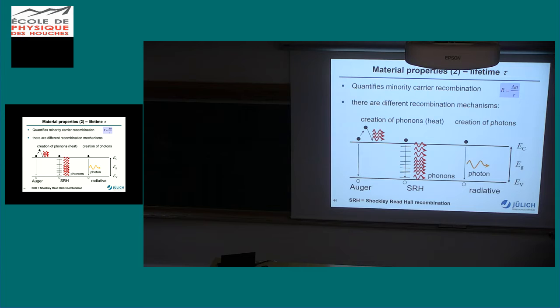But it's also important, for instance, in silicon. Why is it important in silicon? Because in silicon the radiative process is very slow. Silicon is an indirect semiconductor with a low absorption coefficient and a very long radiative lifetime, in the range of hours, I think. So that's not very efficient, but that's a reference. Anything that is smaller than this very slow process in silicon has an influence. And that's why Auger, even if your silicon is not doped at all, is getting important.